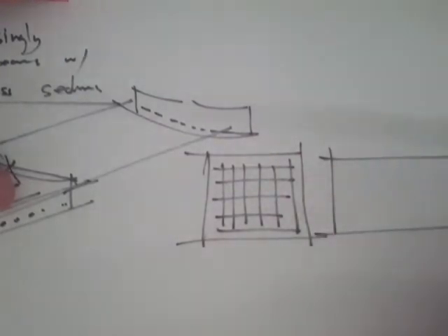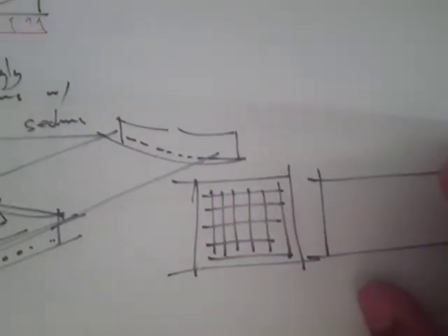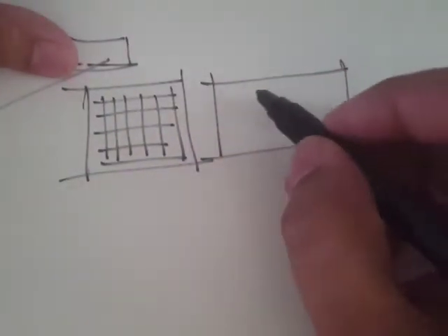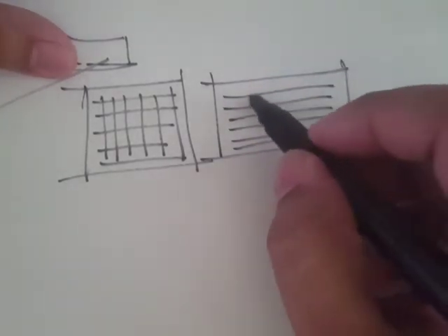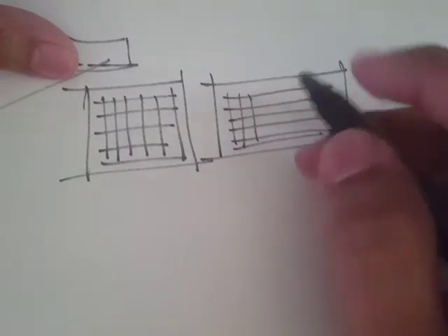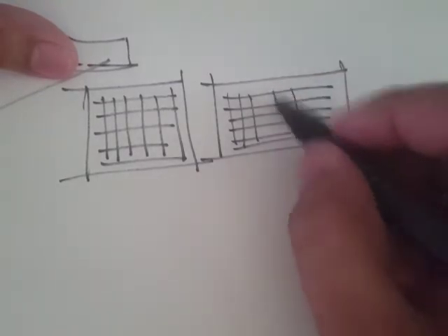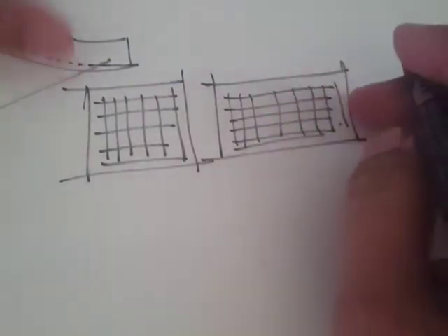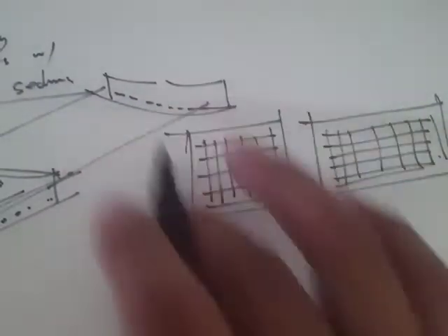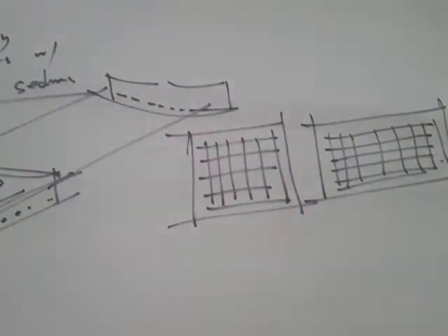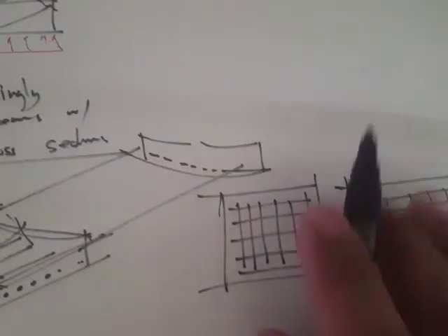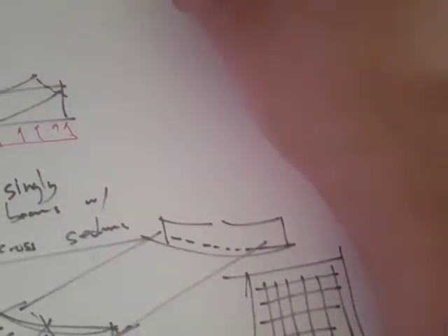But for rectangular footings, there's going to be a different distribution along the long side. So it has some more extra computations because it's not the same all throughout the length. Anyways, since we're just dealing with a square footing, we'll just have uniform spacing.